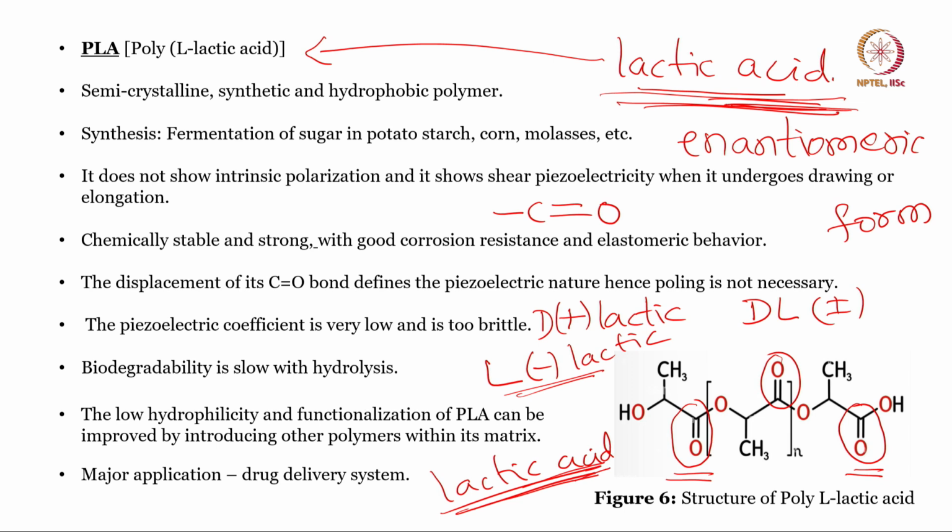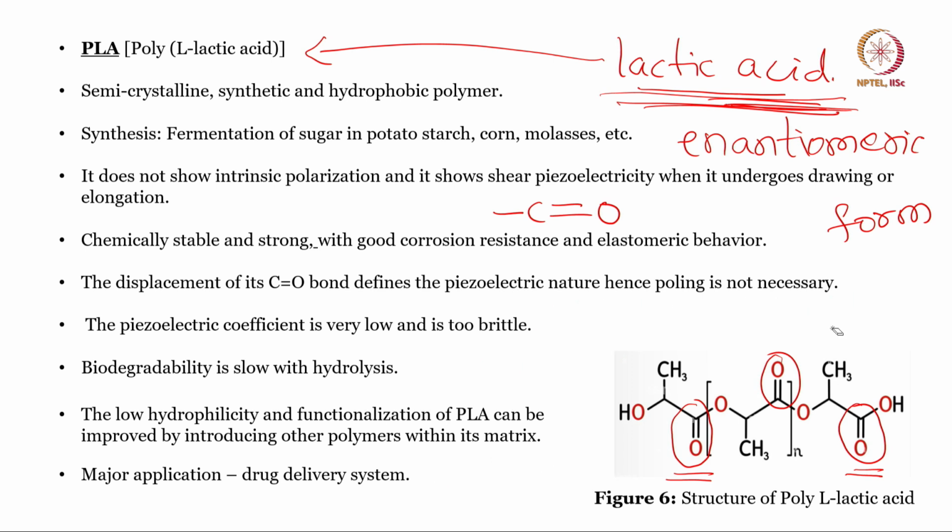Apart from that, polylactic acid is highly brittle in nature. The brittle nature makes it mechanically weak, and the mechanical properties of the material are also very poor. It also has a hydrophobic character, due to which it cannot be properly attached to the cell surface or cell membrane. Due to that reason, it has found less application in tissue engineering fields, and the major application of this material is found in drug delivery systems.